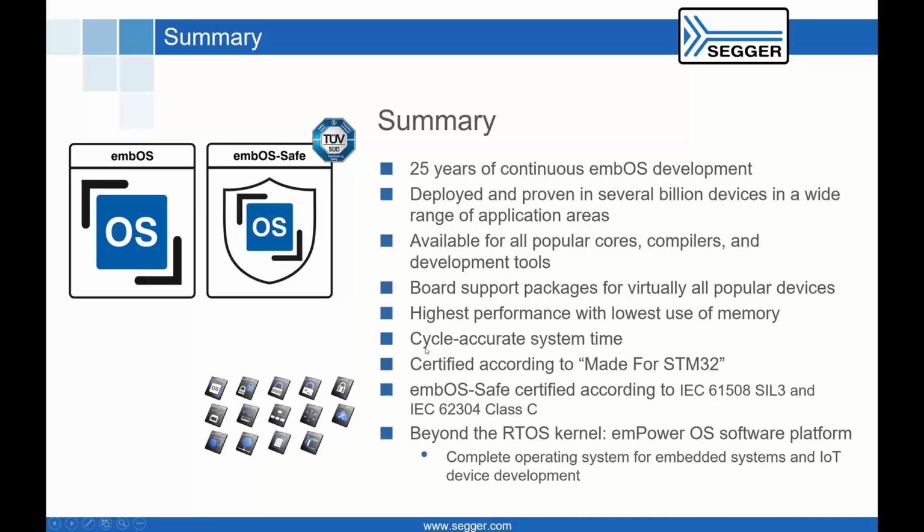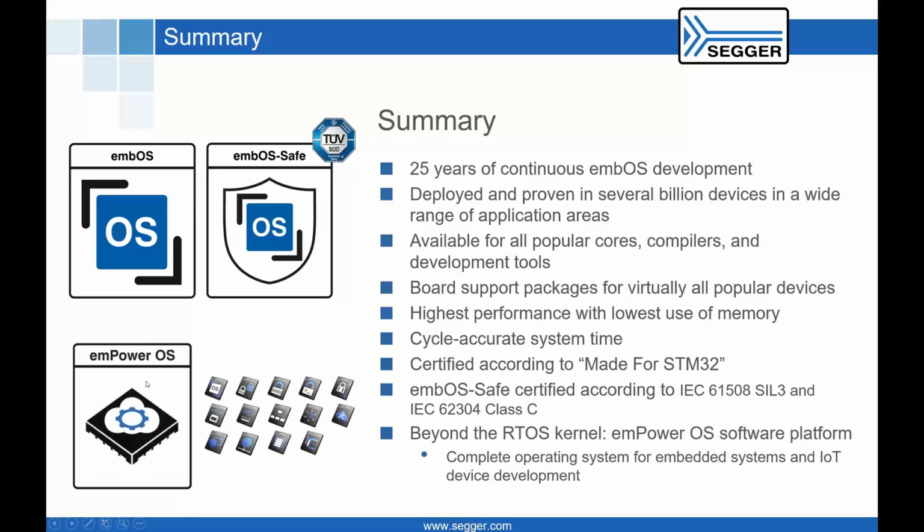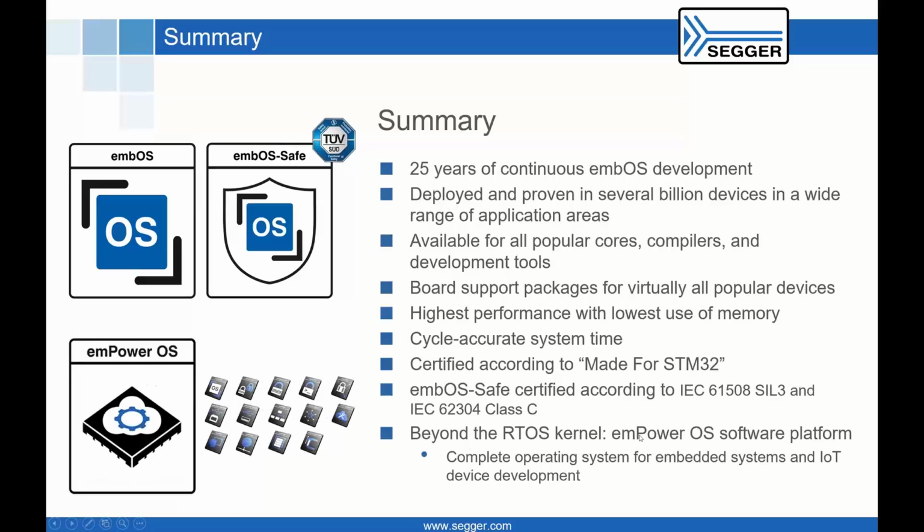We have cycle accurate system time. It's also certified for Made for STM32, which is a program that they started a little while ago. I also mentioned that if you need a safety certified version, we have embOS-Safe, certified to IEC 61508 and 62304. And then basically we have emPower OS as the next step. If you want to go beyond the kernel, that's our complete operating system for embedded systems and IoT device development.